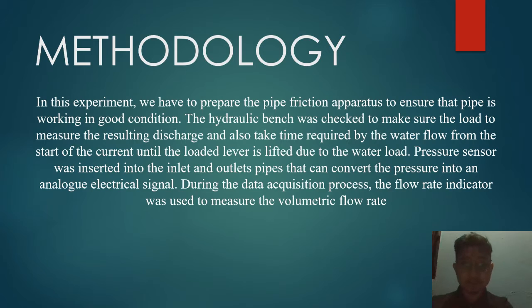In this experiment, we have to prepare the pipe friction apparatus to ensure that the pipe is working in good condition. The hydraulic bench was checked to make sure the load measures the resulting discharge and also takes the time required by the water flow from the start of the current until the load level is lifted due to the water load. Pressure sensor was inserted into the inlet and outlet pipes that can convert the pressure into an analog electrical signal. During the data acquisition process, the flow rate indicator was used to measure the volumetric flow rate.